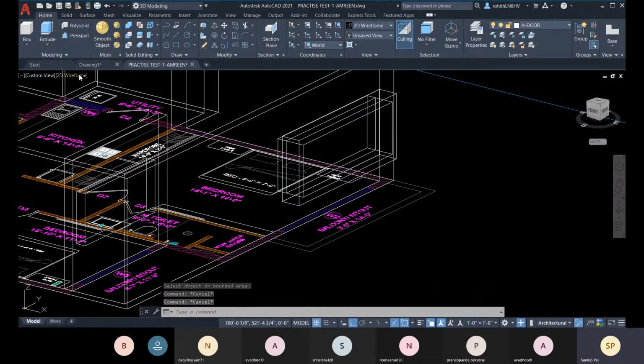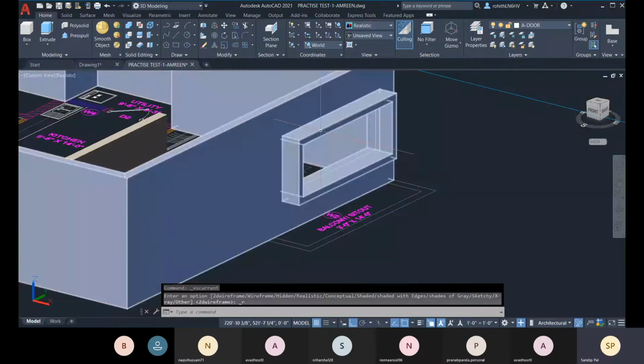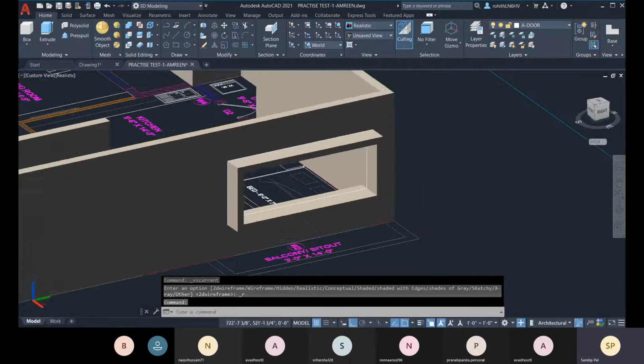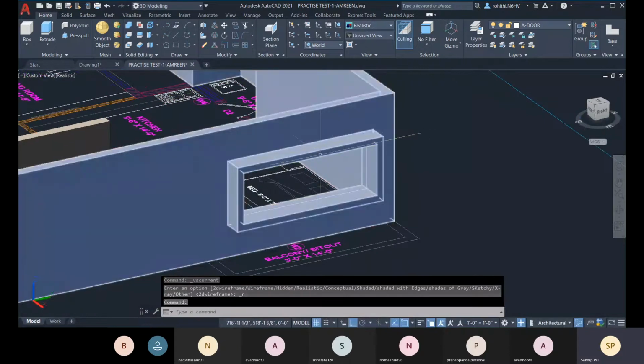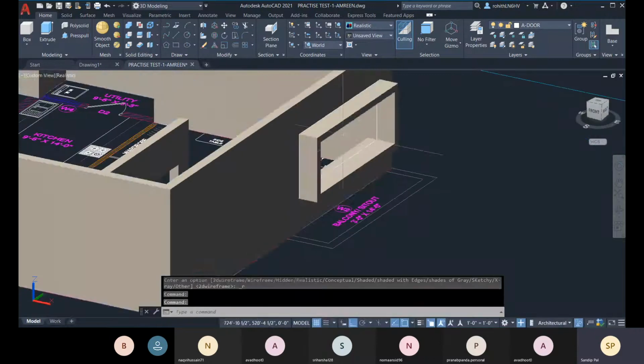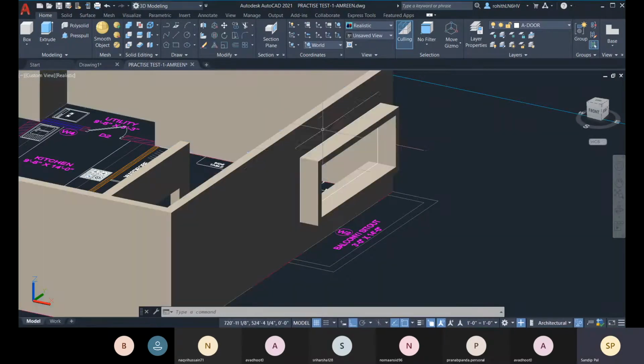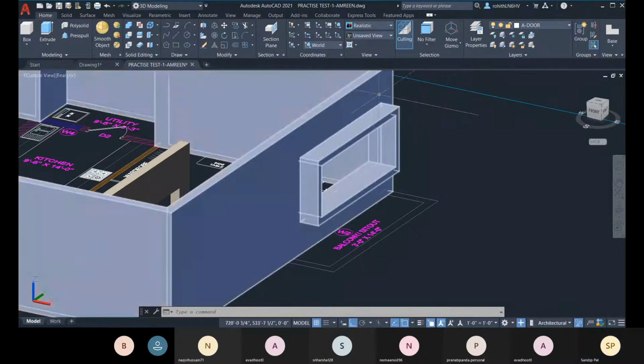This chajja is not a different object. It's not a separate object. If you go with this press pull, it will be part of this element. The area which is defined by those two rectangles is extruded, and that area is part of this element.